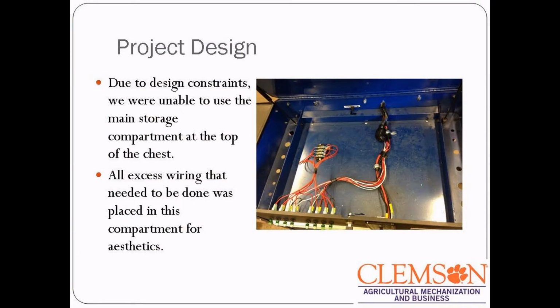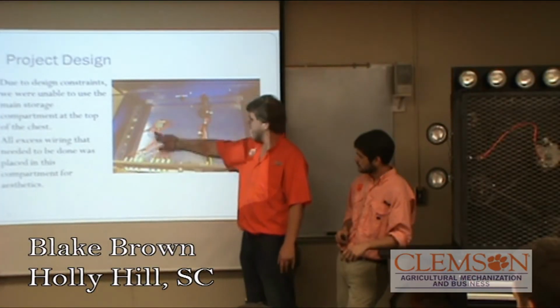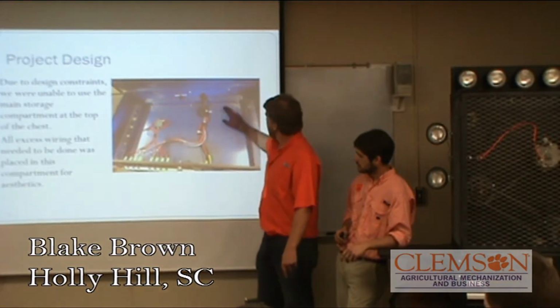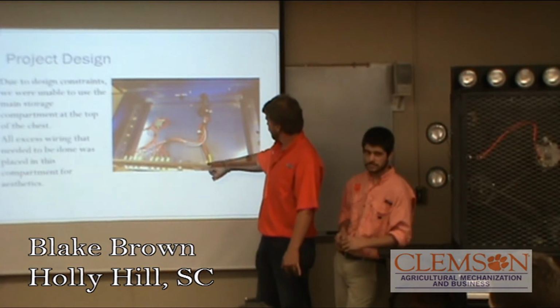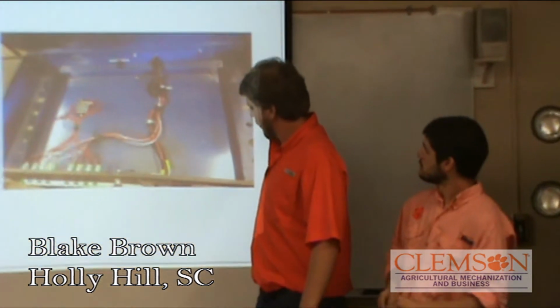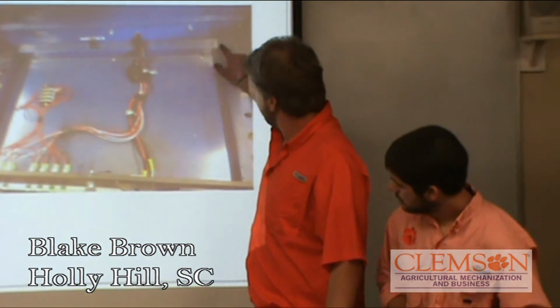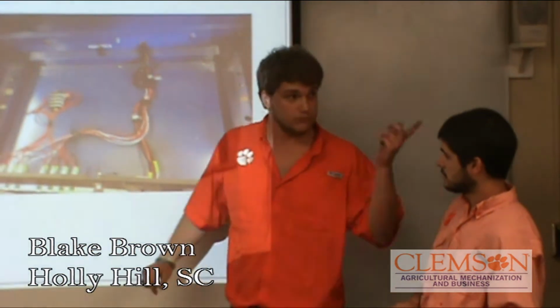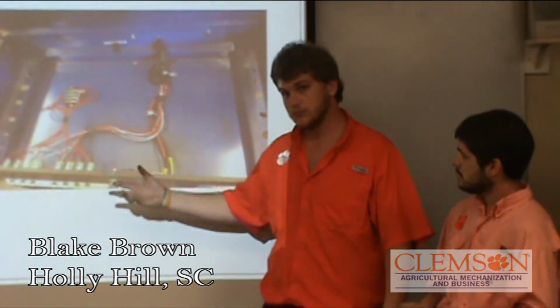So right under here, all our wiring is hidden. As you can see, these are the front switches on the front. This switch bank, we would have a 6-gauge wire running to our battery, and that's what powers these lights. But anyway, we have our switch, and running from here back to our power source, and also to our motor, and then from our motor up to the kill switch, and then back to the motor.